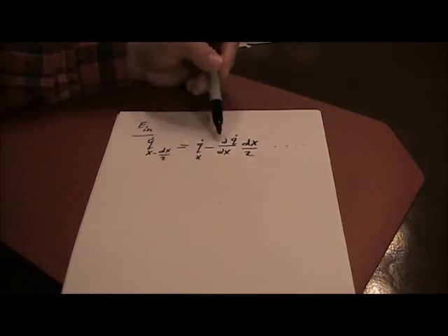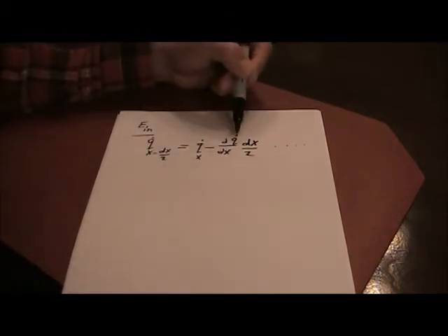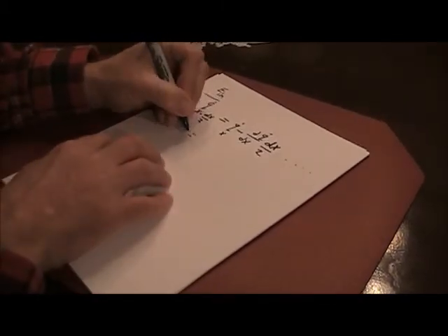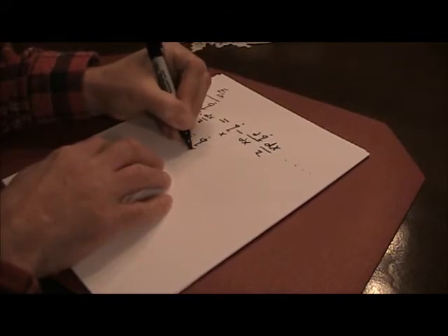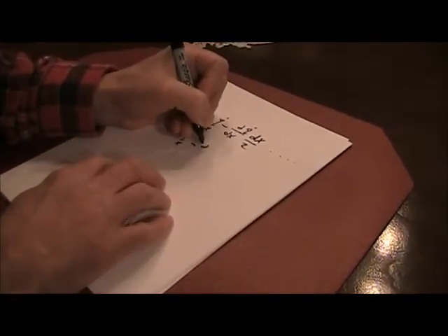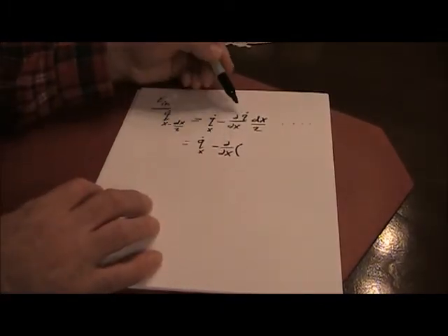Okay, so one more thing we'll do with this equation is for Q, right here, we're going to use Fourier's law of conduction, which of course you know is minus K times the area times delta T over delta X. So if we substitute, what we would have is Q dot at x minus delta x over 2 is equal to Q dot at x minus the change with respect to x, and here's where we throw in Fourier's law for the Q dot.